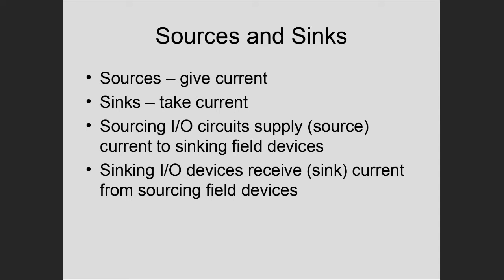So over here, you have another module. This is the output module. And hooked to that screw terminal, you got a light. And we'll say that this source is current, so I'm going to do it like that. So in here, actually in here, in memory, if you close that button right there, then there's these registers in here, those cells I was telling you about. This is like a grid. And what you got to do is you got to map that screw terminal to one of these positions in the register, one of those cells. You got to map that screw terminal to another one. The way you do that is using the address.